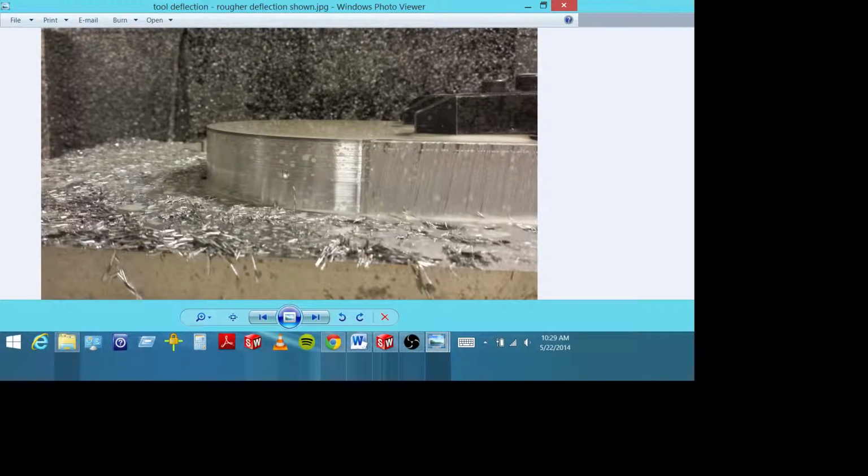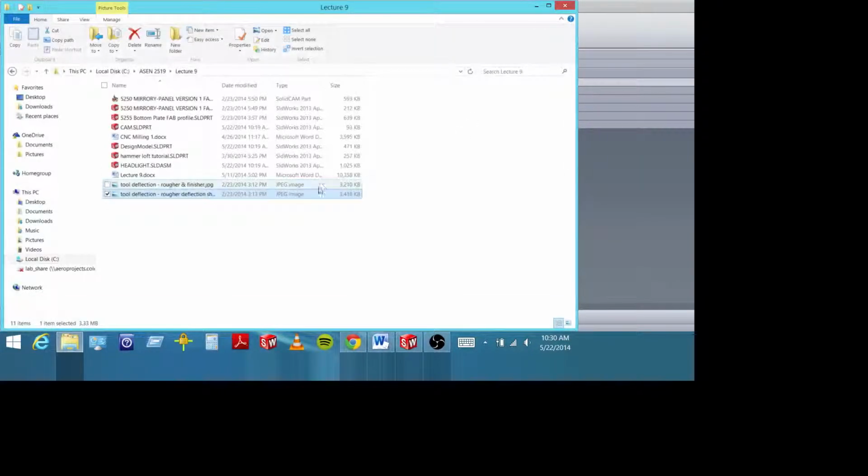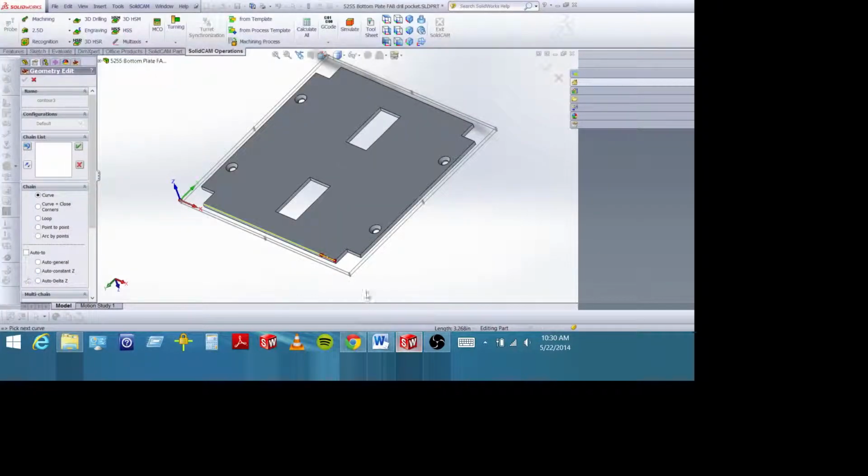If we had been conventional cutting this contour, it would have been into the part. Okay, so when we cut our finisher path, this finisher would have finished up here and it would not have finished down here, which is bad because we would have had to take more material off this diameter to clean that surface up. Okay, so that's tool deflection.